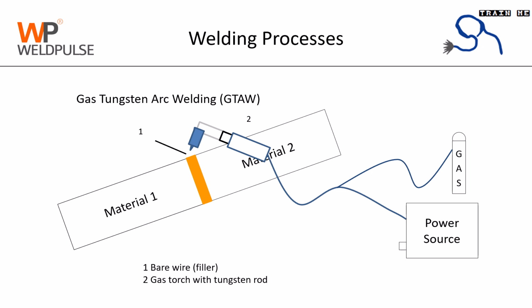Gas tungsten arc welding includes a bare wire as a consumable along with heat and gas. Unlike in the case of shielded metal arc welding, gas is used in GTAW for shielding to avoid oxidation of molten metal during the welding. A tungsten rod is used to produce the arc, and heat is generated to melt the filler wire. This process is slower than shielded metal arc welding, however it produces sound welds. It is normally preferred to perform the root and the hot pass with GTAW.